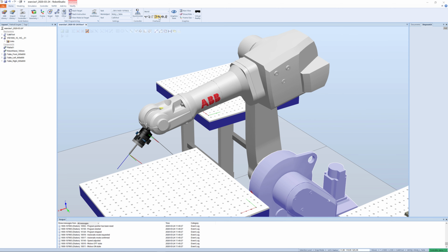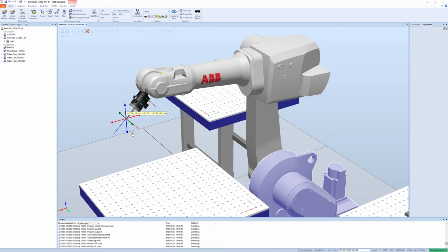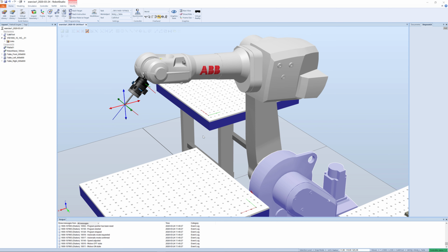Quite simple. If we take linear, so that is moved in that way, and that actually is something we're gonna use when we program the robot in this case. Basically, there are many ways to define robot targets, but we can drag it in a similar way as we would if we were standing physically to the robot, that we'll do in this case, or we can input data taken usually from a CAD system or something.